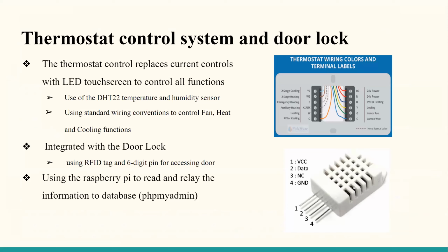This is the thermostat control system and door lock. It's basically replacing a common thermostat control that people have, like an analog one, with an LED touchscreen. It controls all functions such as the fan, heating, and cooling that are common in most thermostats. And it's using a DHT22 temperature and humidity sensor to collect the data of the ambient temperature to either turn on the cooling or turn on the heating, depending on what it is.